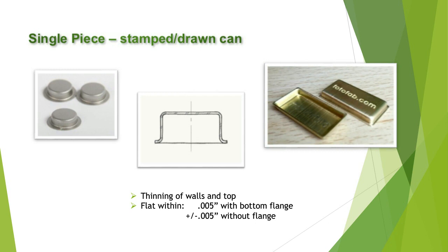This is sort of a high volume application, so if you're in the military business, there are not many people in the U.S. that still make drawn cans. It's mostly gone to Asia for high volume electronics production. If you do need one of these, though, I would advise you to work closely with the vendor because traditional bend math does not work.